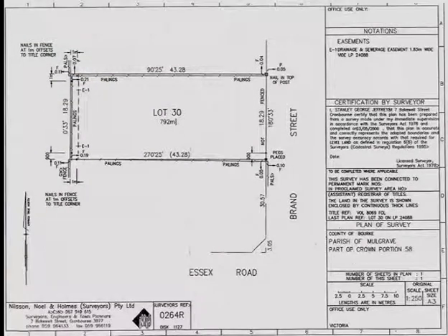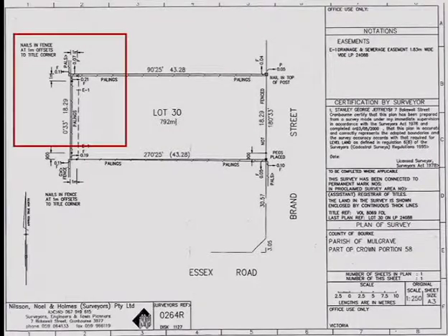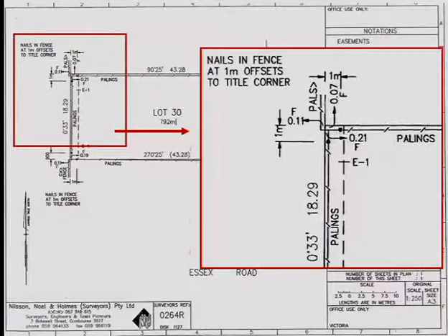Here's what the land surveyor will give you, an example of something that they'll give you to confirm that information. You can see here at the back of the property, there's a difference between the fence that's on the site and where the... So here's the fence. You see that dashed line with the diagonal? That's showing the fence, and that's the legal title boundary.